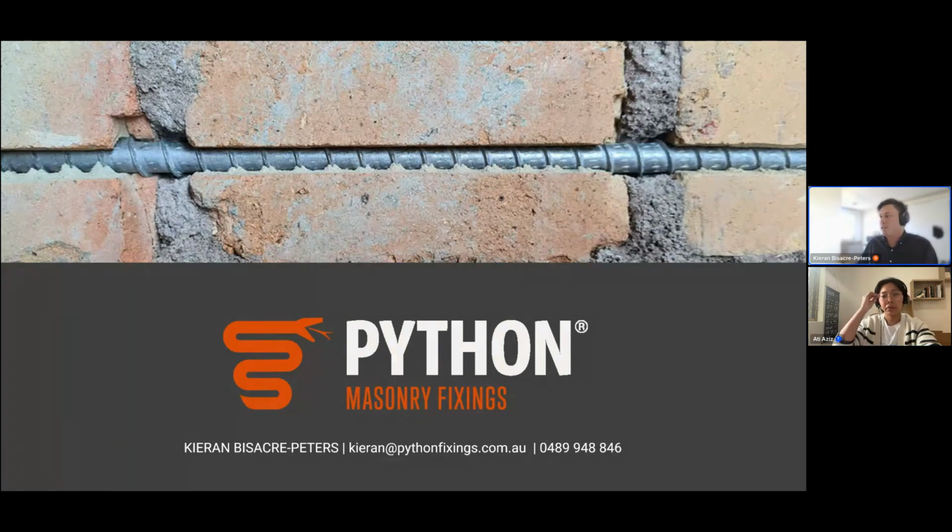That's a good question. Cracking in masonry structures is generally caused by settlement. You can stitch the cracks structurally using wire products with epoxy systems and then grout over the cracks. But generally that just redistributes the stresses to another area and you get other cracks occurring across the building. So the best way to address that is to address the root cause of the problem and strengthen the foundation so that you're not getting that settlement with the shrink-swell cycles of the ground.